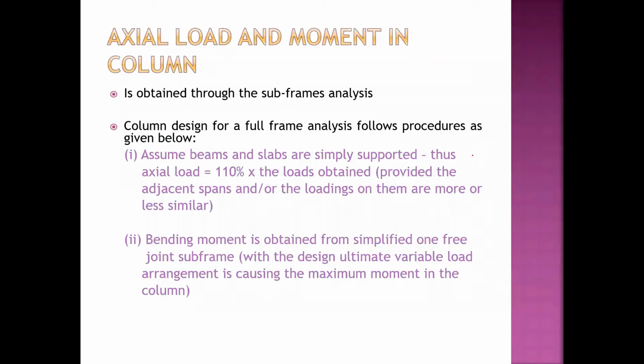Axial loads and moment in column. The axial load and the moment are obtained through the subframe analysis. For the column design, for a full frame analysis, follow the procedures given below. Number 1, we assume that the beams and slabs are simply supported. This is on how to determine the axial load, or N. Thus the axial load is equal to 110% times the load obtained, on condition that the adjacent spans and or the loadings on them are more or less similar.